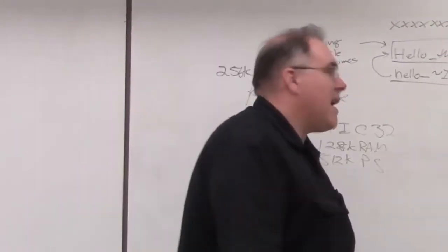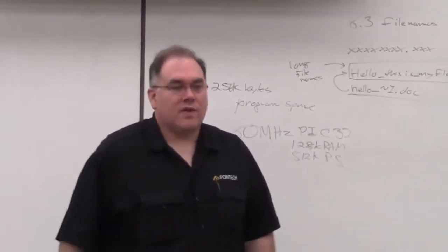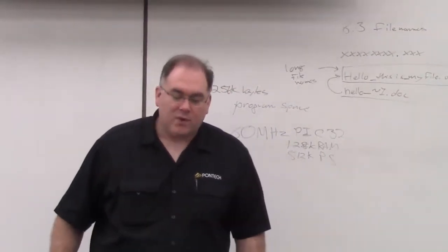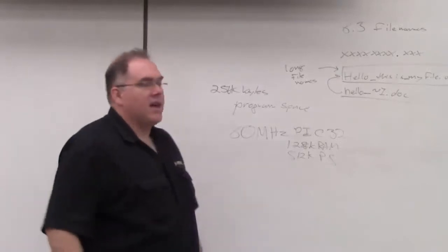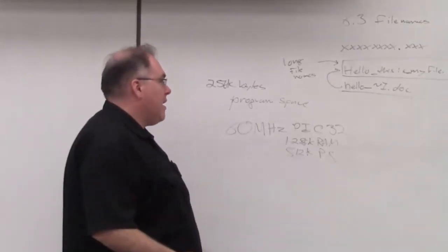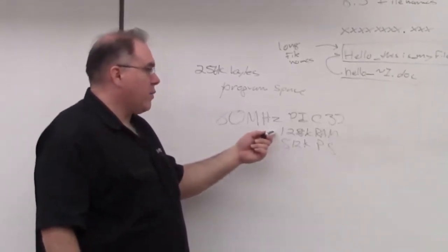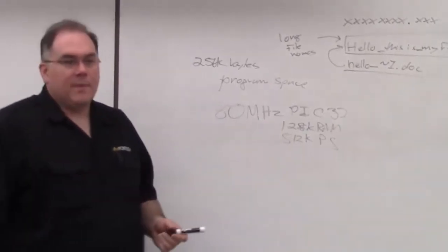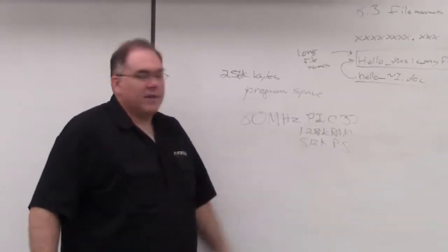Gary's question was, can you store programs in there? And I kind of gave a yes, right? So the problem is, in order to do that, you would have to load the program out of the SD card and put it into RAM and run it out of RAM. That is not a trivial thing to do.